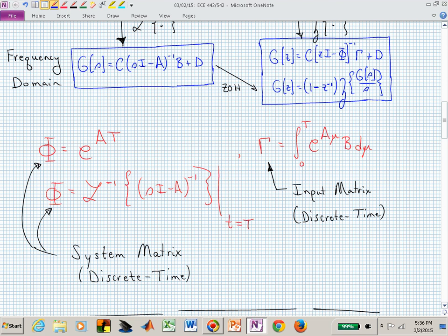And what's appropriately in this class so far? If you're listening along online, you won't see me animating this rule of thumb that I was trying to indicate. I was sticking my thumb in the air. What's our rule of thumb for picking capital T? 30 times the closed loop bandwidth.